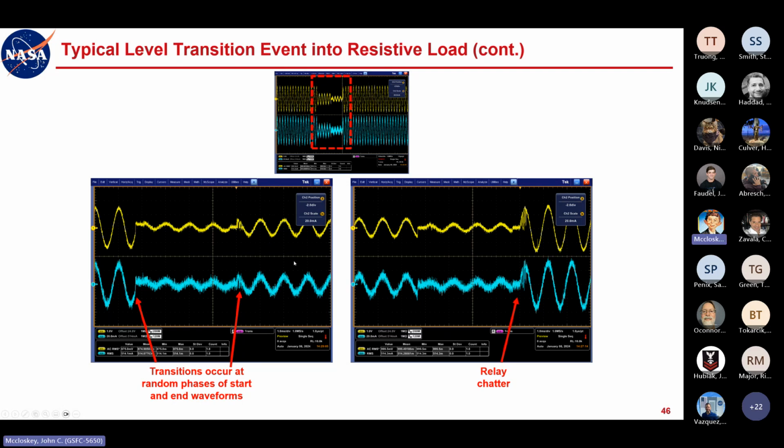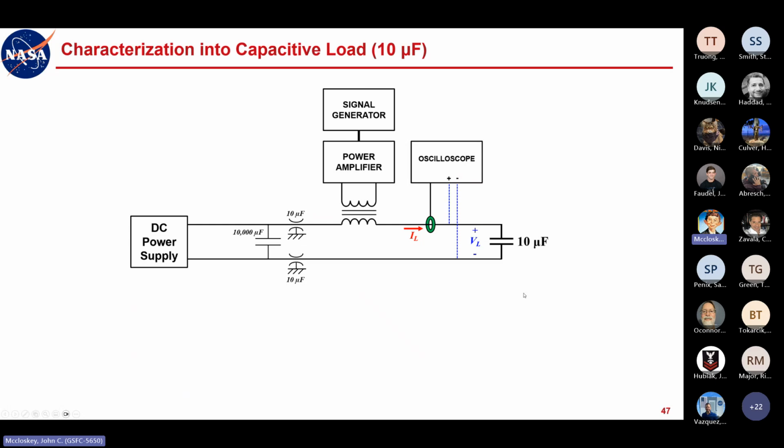amplitude. So again, with a lot of these circuits, it's the di/dt or the dV/dt rather than the absolute magnitude of either that can cause problems. And here this is most likely relay chatter. We could actually hear the relays clicking inside the unit when it was most likely going from one drive circuit to another, to get you from one drive level range to another range. So you could hear the relay chatter as it was making those transitions, and it was giving you these abrupt transitions or this kind of ringing here before the level actually settled down.